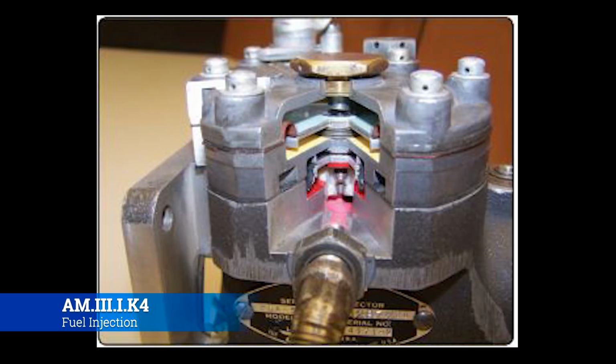Okay, so this is a cutaway view of the airflow measuring section. The airflow consumption of the engine is measured by sensing impact pressure and venturi throat pressure in the throttle body. The pressures are vented to the two sides of the air diaphragm. Now this shows the measuring section, and the movement of the throttle valve causes a change in engine air consumption. This results in a change in the air velocity in the venturi. Now, when the airflow through the engine increases, the pressure on the left of the diaphragm is lowered due to the drop in pressure in the venturi throat.